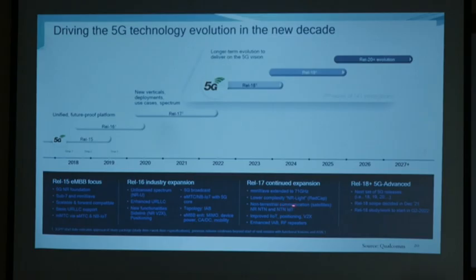Okay. And release 17 also introduced two more very important studies. One is called non-terrestrial communication. This is integrating the terrestrial and non-terrestrial network, and another one is non-terrestrial IoT. These are the two study items introduced in release 17. Okay, improved IoT and position accuracy and vehicle to X communication, enhanced IAB. IAB means integrated access and backhauling. So the millimeter wave frequency cannot travel very far because of the path loss, etc. So we need to introduce a kind of relay network that's called integrated access and backhaul, which is introduced in release 16 and release 17 as well.